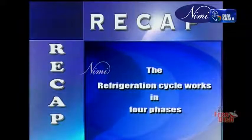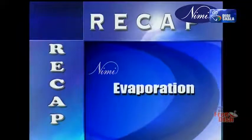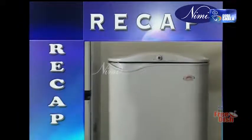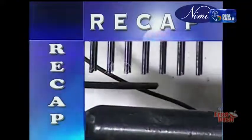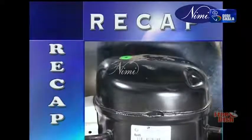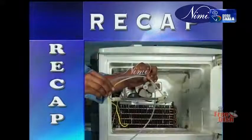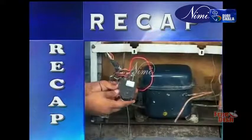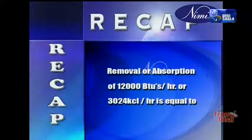The refrigeration cycle works in 4 phases: compression, condensation, expansion, evaporation. The conventional refrigerator consists of components like compressor, condenser, capillary tube, expansion device, evaporator, filter. The frost-free refrigerator consists of compressor, condenser, filter, capillary tube, expansion device, evaporator, evaporator motor, defrosting heater, temperature control, and timer.